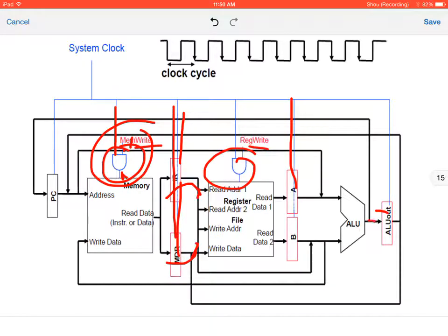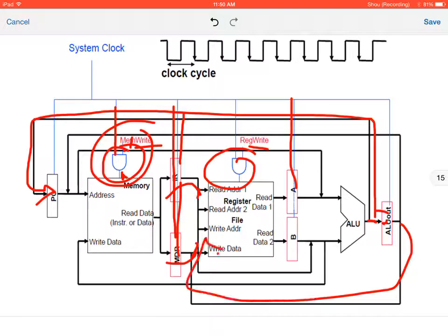Same thing with ALU. Here, if we're doing this, the reason why we'd be waiting for the next cycle is because we want our types to take 4 cycles. But if this value is being calculated here, that means we've calculated some sort of branch instruction, which means we want the instruction to be done immediately. So it's not going to wait for the clock.